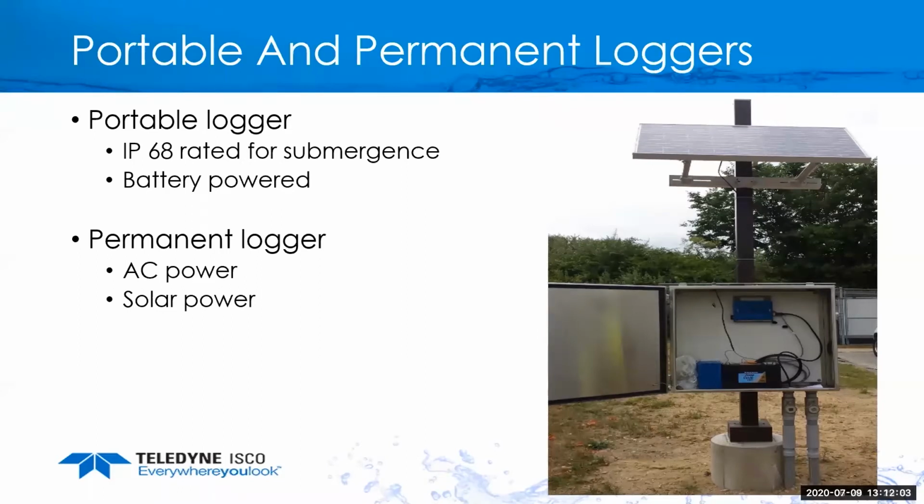A lot of what you need to look at is what is your ultimate goal? Do you need a local display? If you don't, a lot of times people will just run either analog output signals to a PLC. A lot of times you could do Modbus to a PLC. In this case, they are going to go with cellular. So you have cellular modems that are transmitting the data as well. So need to determine what your ultimate goal is on the power option.